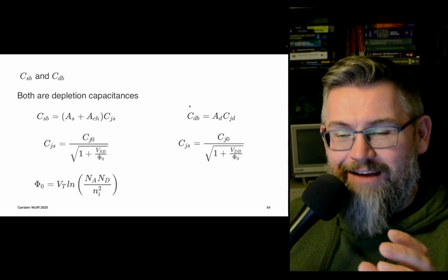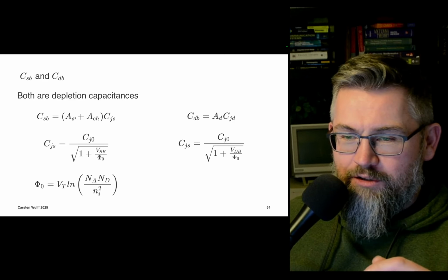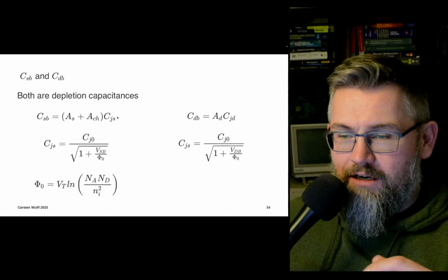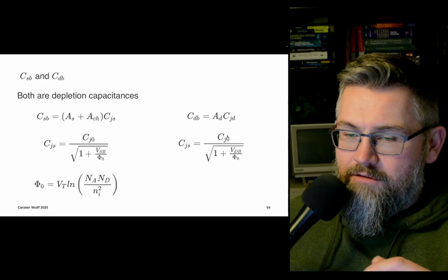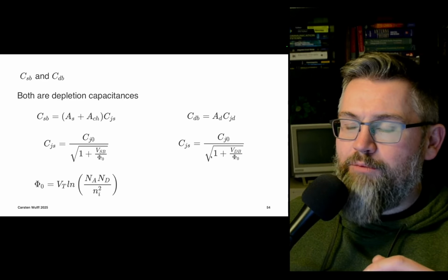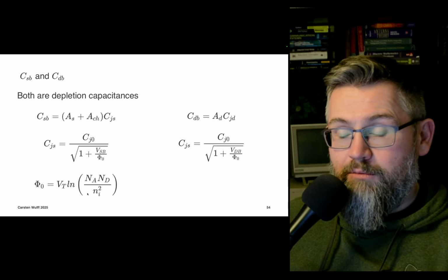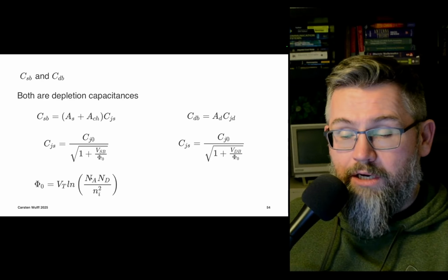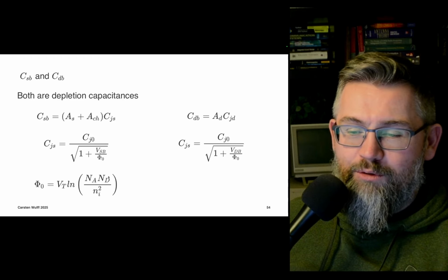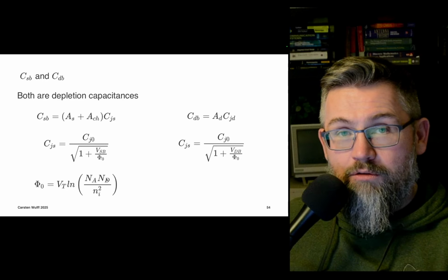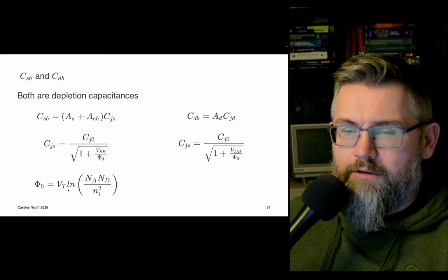So when you have a P and then you have an N. And the capacitance is then given by some sort of area of the source and the channel, in this case, and this junction capacitance, which is some number divided by a function that goes as the square root of the voltage across it, where the built-in potential you can see down here. So here we can recognize the density of acceptor dopants and density of donors, and the intrinsic carrier concentration and thermal voltage.